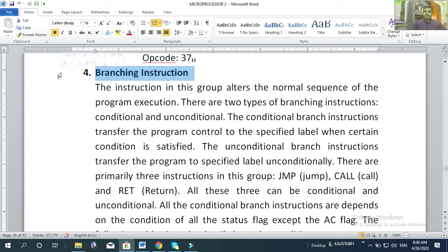Since the 8085 is an 8-bit processor, each memory location should have provision for 8 bits. All the opcodes in the 8085 are 8-bit, and data is also 8-bit. Therefore, for each opcode and data, you need one memory location. So the entire program has to be written in sequential locations in a block of memory.